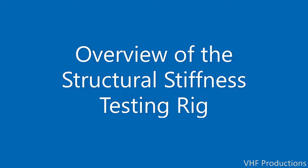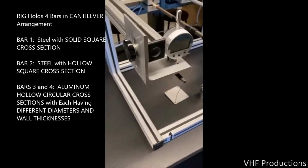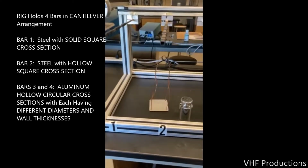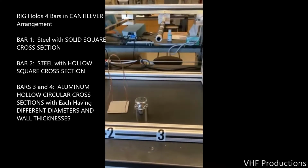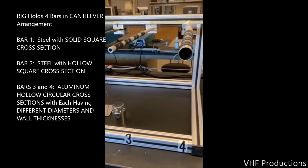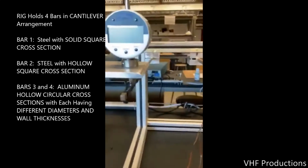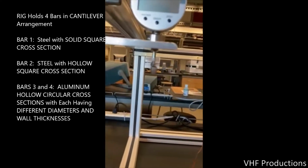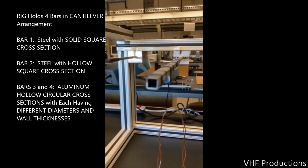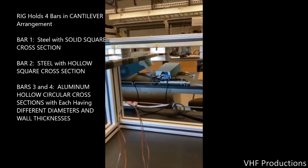Now let's move on to measuring the deflections of our single cantilever beams used in this experiment. The first beam, number 1, is the solid cross-section steel beam. To measure its deflection under load, we have a small deflection gauge that can be set up against the surface of the beam exactly at the point where we're going to apply the load. This is a very simple displacement gauge that can be read directly on its face, the displacement of the gauge relative to the beam for each loading configuration.